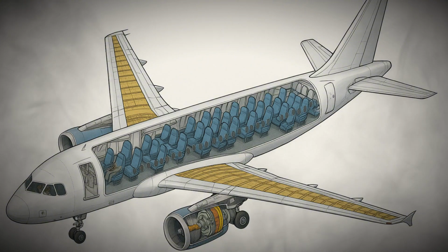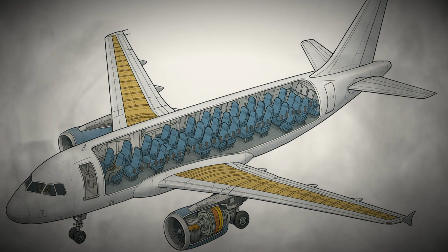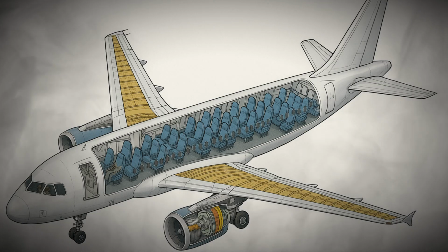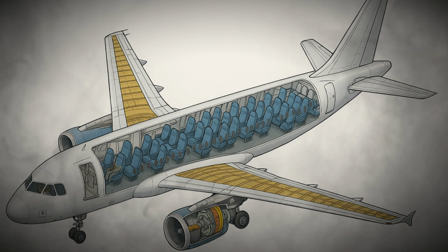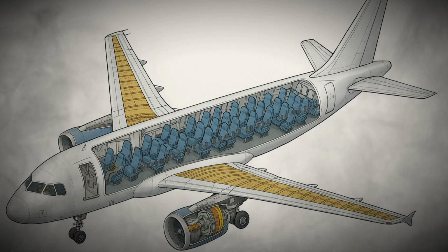Both takeoff and landing are influenced heavily by weather conditions. Strong crosswinds, low visibility, rain, snow, or icy runways increase risk and demand greater skill from pilots. Aircraft performance charts account for temperature, pressure altitude, and runway conditions to determine required runway length and safe speeds.